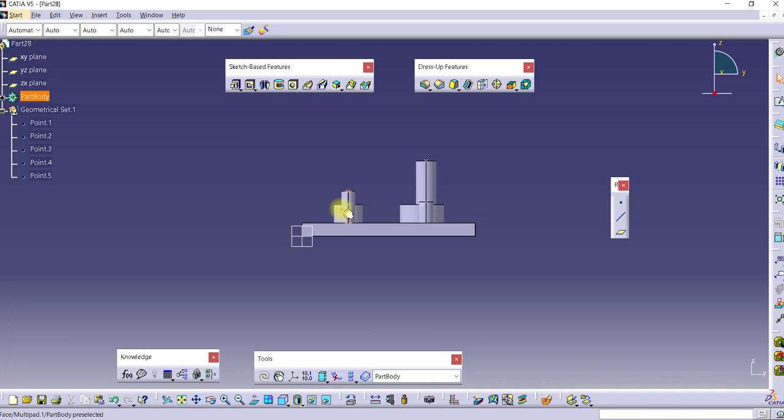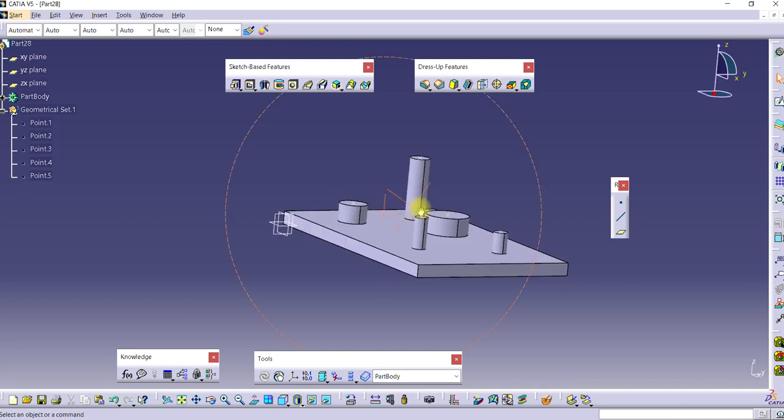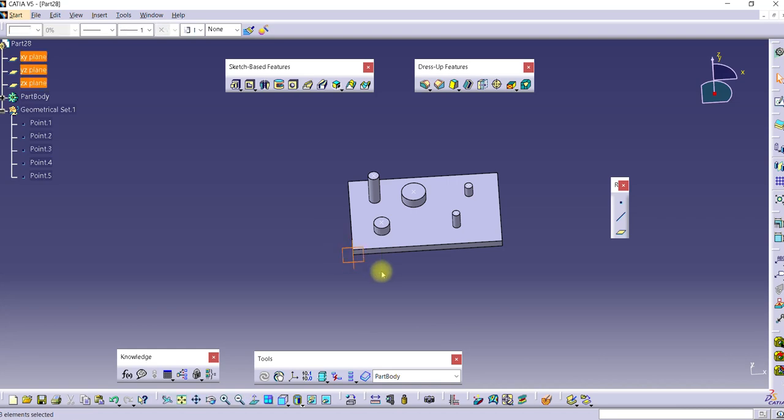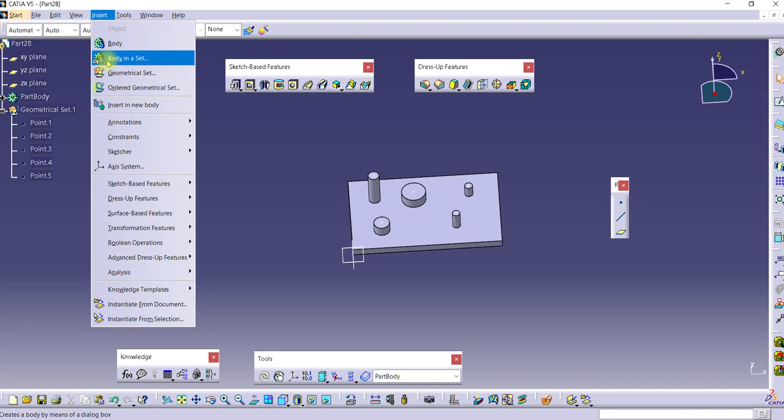So we can extract all the X, Y, and Z coordinates. And then one more, we need to define the new system for our reference, because sometimes, for example, if you want to do the check in the picture, you have a different datum, so you can define the new datum or new axis system.